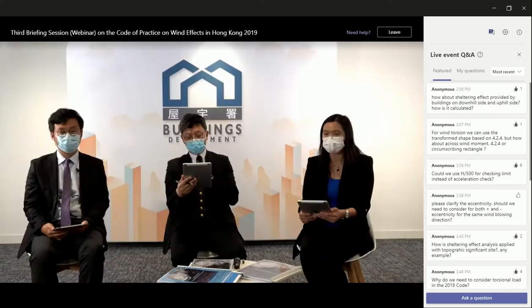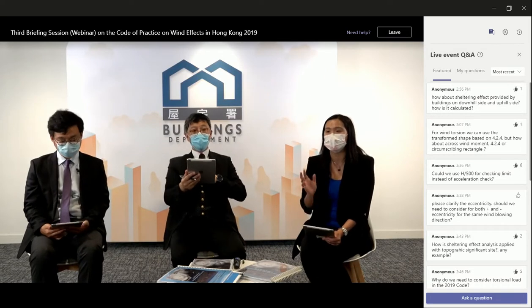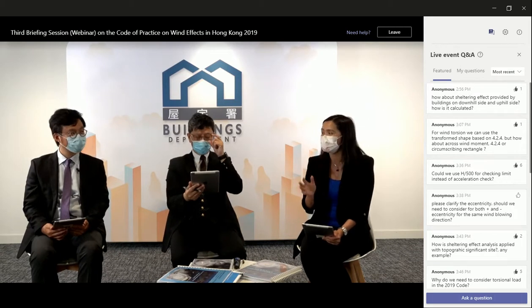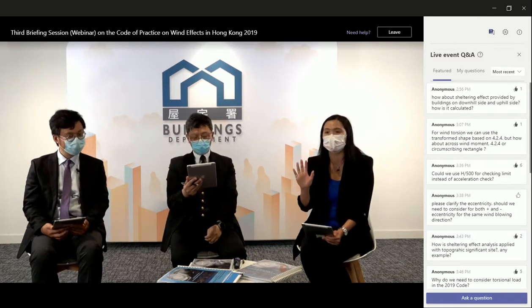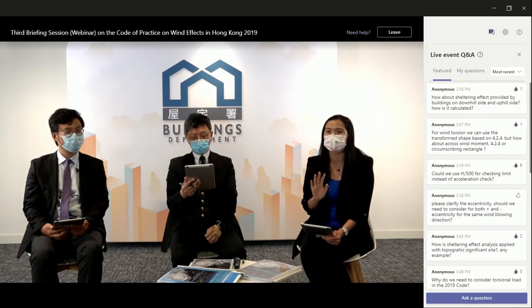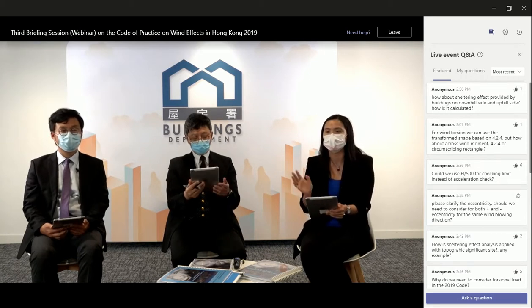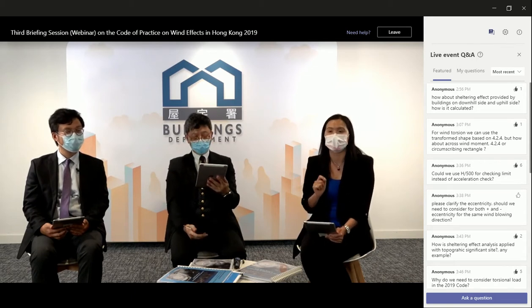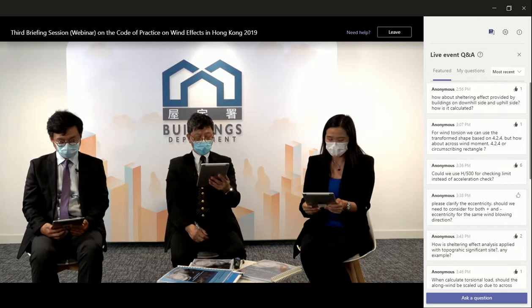Yes. So I would like to suggest that designers not misunderstand that this torsion is to cater for the eccentricity between the center of rigidity and the load center. This is not the case. Actually, the torsion in this code is generated by the non-uniform wind load on the building. The gust wind is not blowing at the same pressure over the whole building. So remember, don't misinterpret this clause. This is in addition to the torsion we normally design for due to the eccentricity of the load center and the center of rigidity.